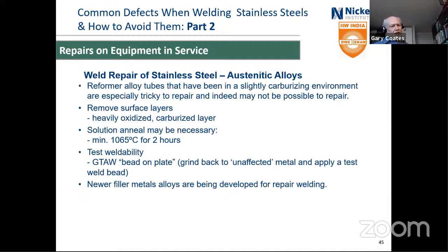You may have to do a solution anneal at 1065 for 2 hours, which is a typical treatment. That's obviously not very easy to do when it's in situ, but these reformer furnaces are huge. If you really try to get it back up online, you really want to do it in place. It's expensive, but it is often the only way to do it.